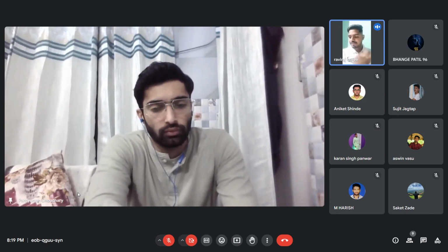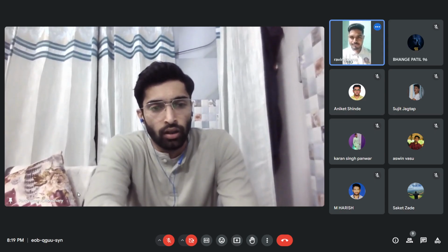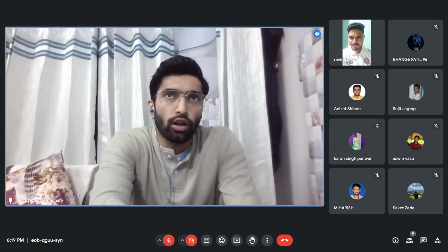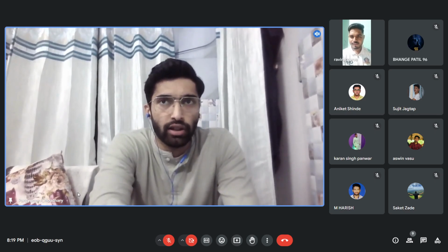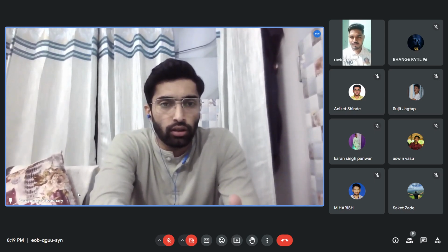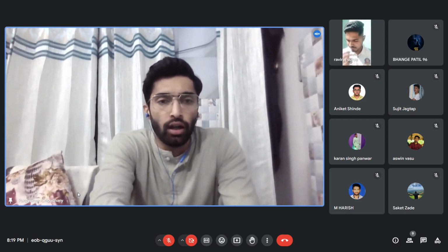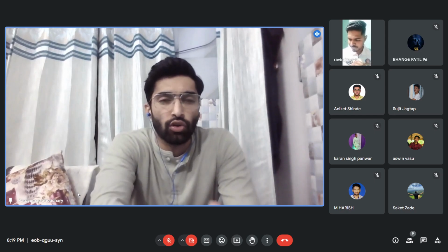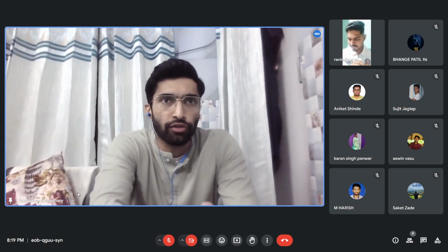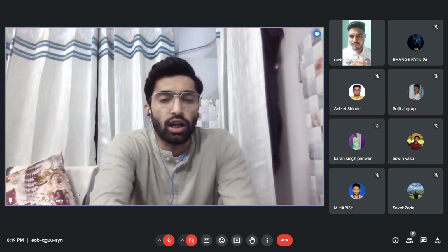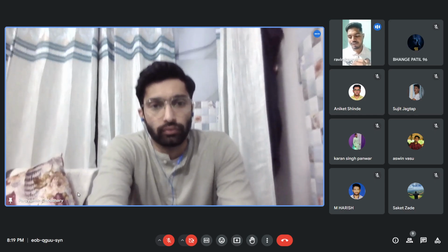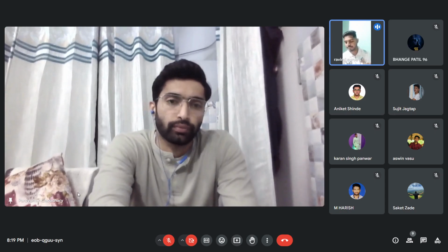So Pradyuman, tell me the safeties of compressors. Yeah, bro. So first of all, low lube oil pressure trip. Then the second one is the safety or relief valve, and the third one is the bursting disk. Fourth one is water jacket temperature cutout or sensor. Fifth one is high air temperature trip, and sixth one is unloader. Okay, so these are the safeties, right? Yep.